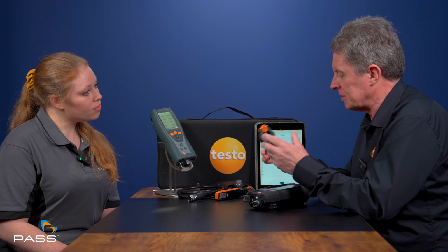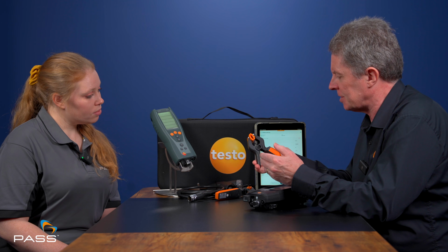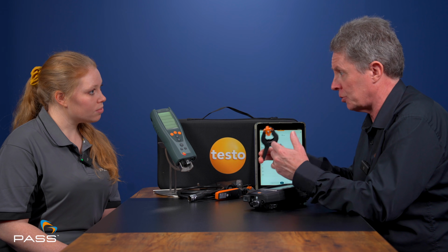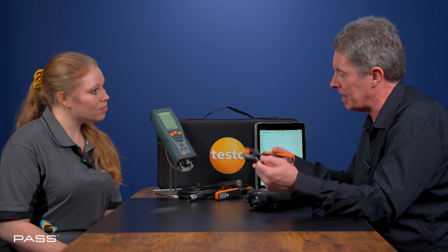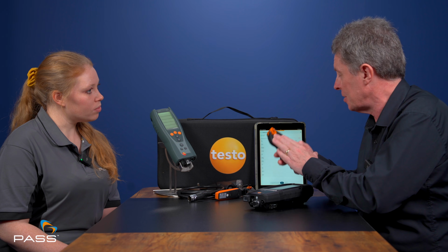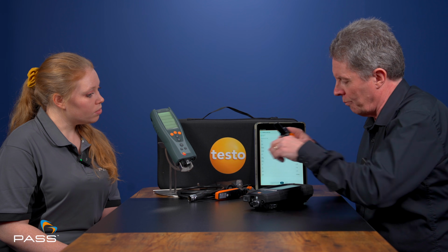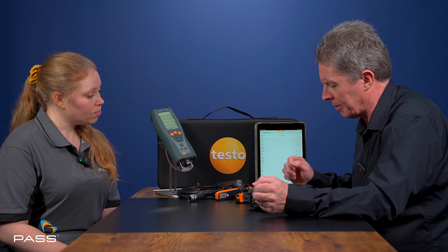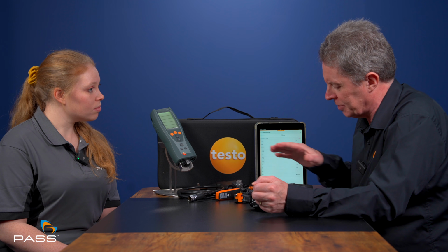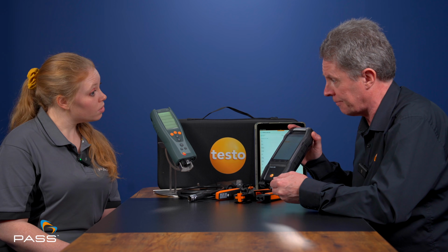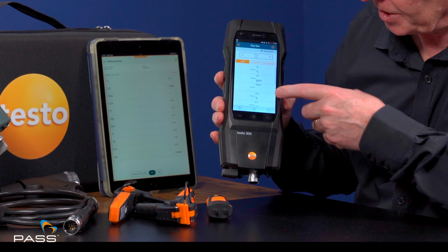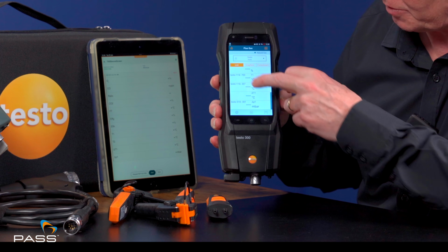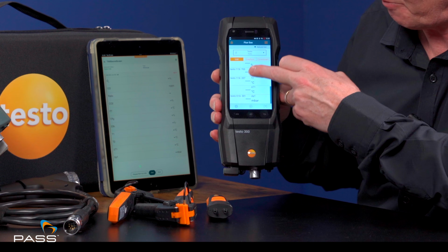These have been used for many years by heating engineers. The classic is to do 2 clamps to do flow and return, or maybe across a radiator where you're balancing a radiator. And these can be used simply with the app. What we've also got with the 300, and this is functionality we introduced about a year ago, is that the smart probes now also talk to this as a device. So for example, here we can see on the bottom of the screen, I've got my 2 clamp probes showing my flow and return temperatures.